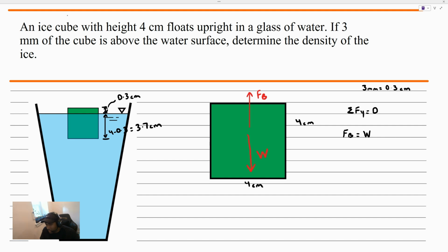we can take the density of that object times gravity. Density times gravity is defined as the specific weight. So in order to compute the weight of that ice cube, what we could do is we could take gamma of ice and multiply it by the volume of ice. If you recall, gamma's units are newtons per cubic meter. If we multiply it by a cubic meter, what we would get is the weight.